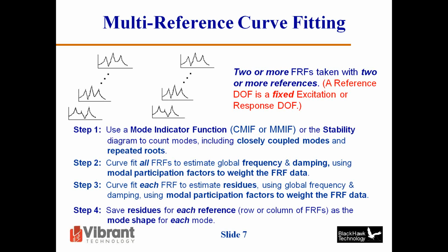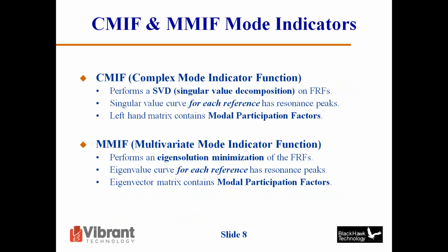Then on the backside, when we come out, we use those participation factors to compute the residues, which again are the mode shape components, or the numerators of the FRF analytical model. Finally, we save each reference of data, and we can animate to look at the mode shapes.